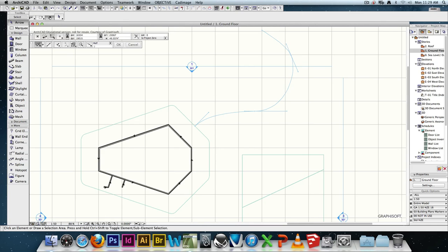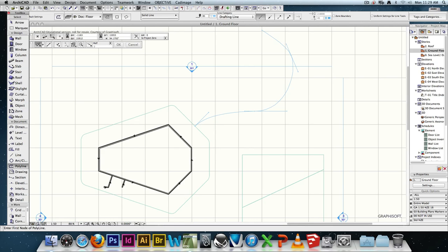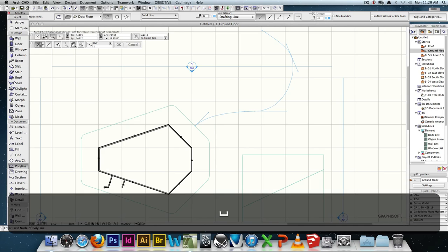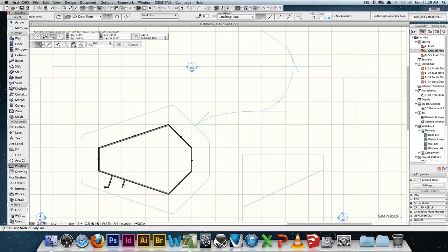So how do we do this? Well, quite simple actually. We can either use a polyline or even arcs and circles. I tend to like to use a polyline. A polyline is simply lots of lines all joined together. So it's straight lines and curves all joined together into one big, nice polyline. And I'm going to hit spacebar, which is my magic wand, and magic wand my spline.